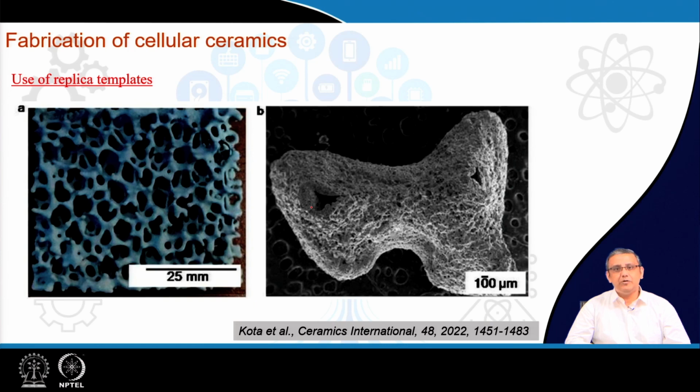Then we have those triangular channels inside the ceramic struts, which form because the polymer foam used for the initial coating got burned during pyrolysis, and from that this continuous triangular channel structure formed.